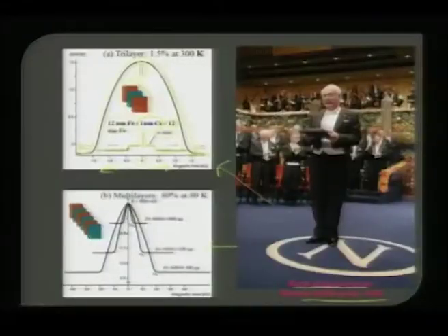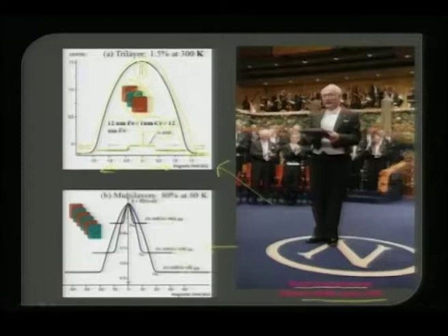So Albert Fert brought out this notion. He said, I can try to make several of these bilayers instead of just a trilayer, and everywhere I will try to change the spacer layer thickness. That is what he did. If you have chromium as 1.8 nanometer or 1.2 nanometer or 0.9 nanometer, as you bring down the spacer layer smaller and smaller, you can see there is a tremendous fall in resistance, and also the field sensitivity is quite high compared to even this example.